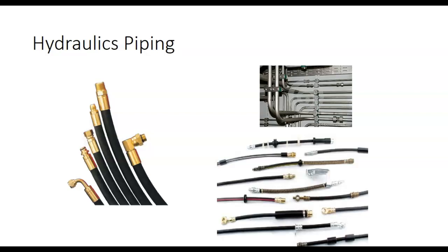Well, our pumps are 3,000 psi. So if you had 1 square inch of area, we could create 3,000 pounds of pressure or force on those things. So that's the biggest advantage of hydraulics. First, you don't have to pressurize it. The problem we have with pneumatics is it's constantly trying to unpressurize itself, right? Hydraulics, we don't do that.